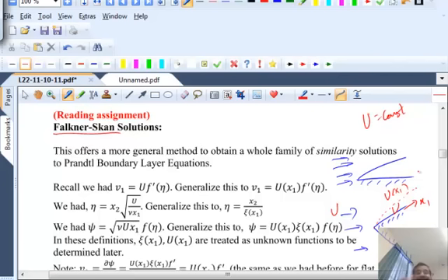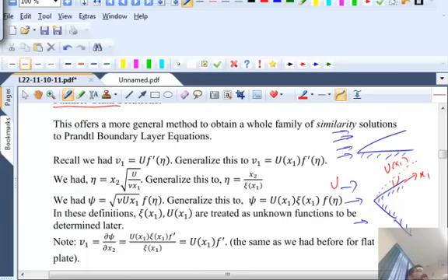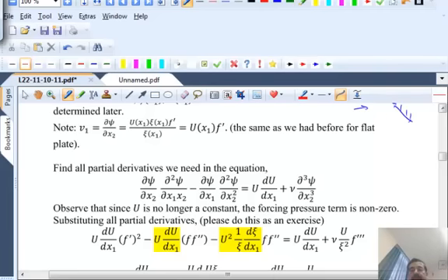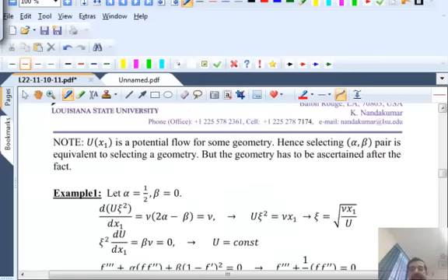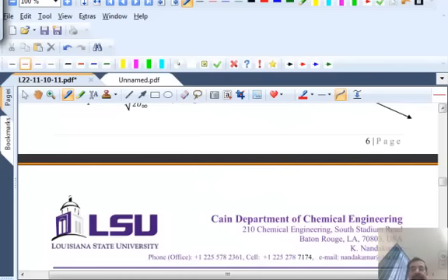Now you will have a non-zero pressure distribution, and it basically takes you through the same mathematics that will allow you to construct a similarity transformation and a solution for a whole class of geometries like that, sectors of various angles, alpha. You can even have alpha equal to 180, then you will have an impinging stream, a boundary layer development near the stagnation flow. So the mathematics is basically the same. Okay, so I want you to look at that and be prepared for the final exam.